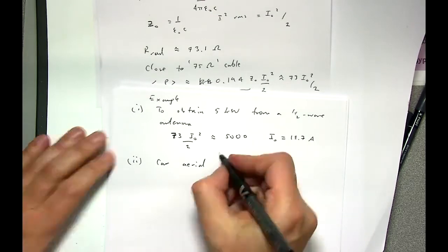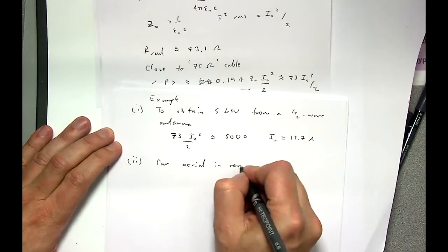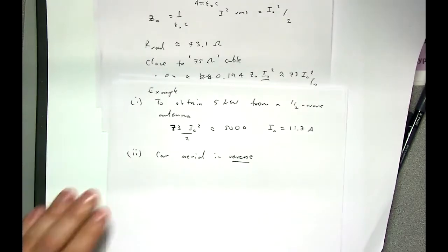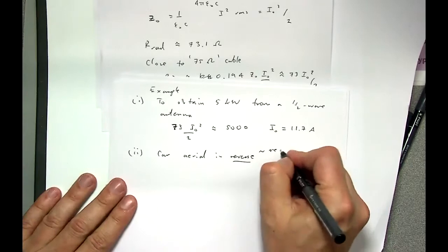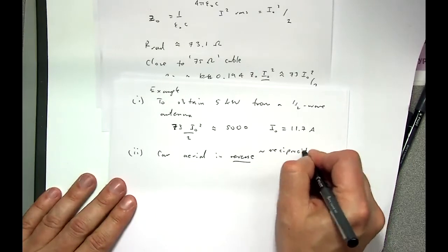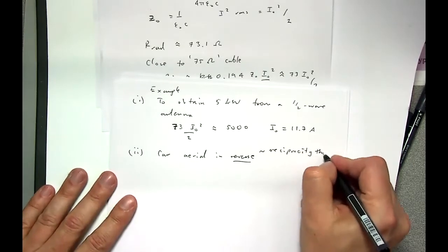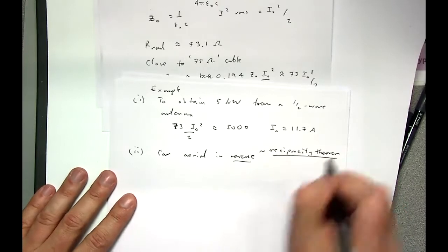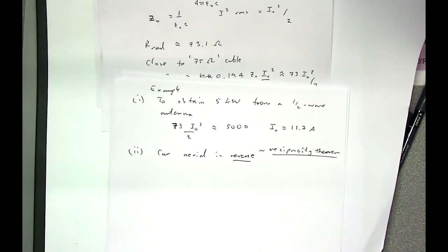Okay? Now the first thing is, of course, it works in reverse. It's receiving rather than transmitting, but obviously you know from the Reciprocity Theorem in physics that receiving and transmitting are much the same. So if I have a plane wave passing over the antenna, it will generate the motions of charges, and the same thing happens in reverse, that for a given frequency I can resonate the antenna and it will give me a signal out the other end.